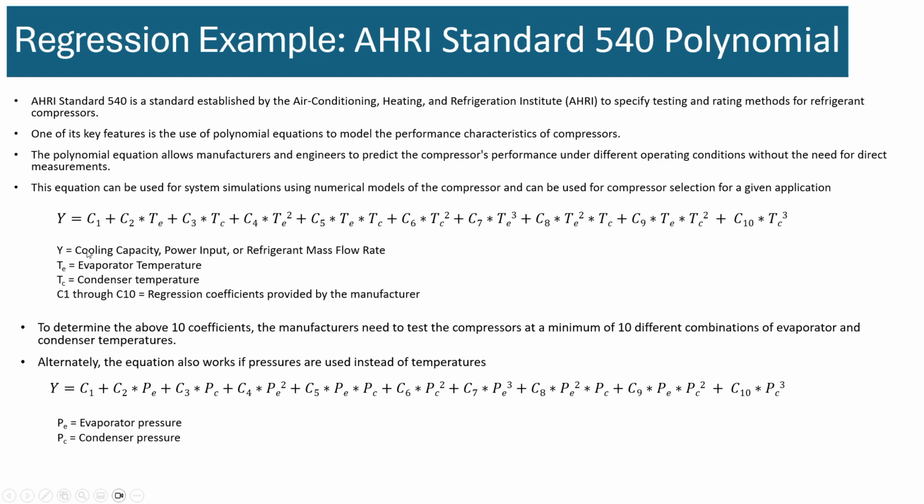When you're looking at the performance of a compressor, you're trying to figure out how much it can cool when the evaporator temperature and condenser temperature are so and so. How much power will it consume from the electrical line at those temperatures? And what is the refrigerant mass flow rate? This is typically used by people who run simulations. If you provide this curve to them, they can use it as a model of the compressor to run virtual systems using dynamic simulations.